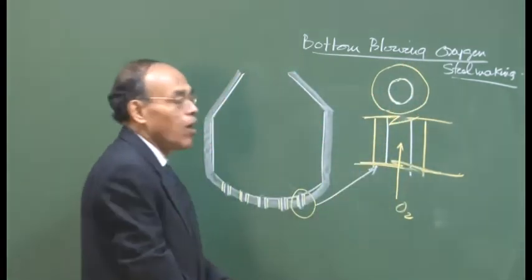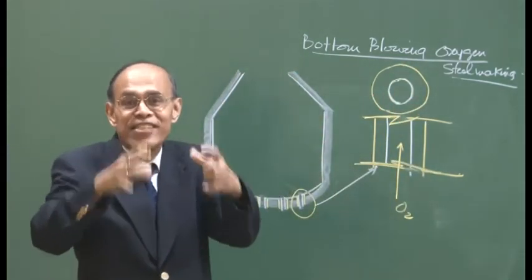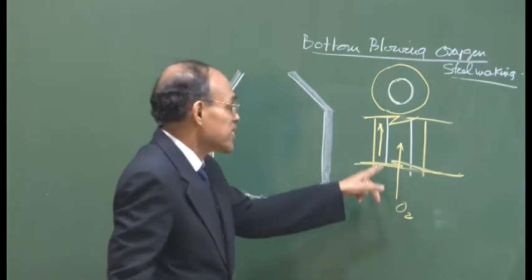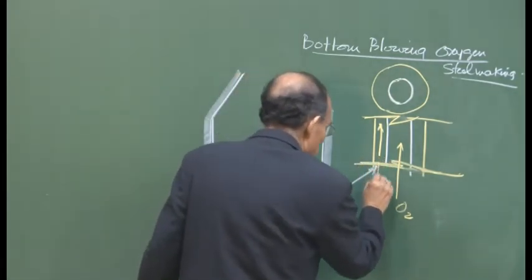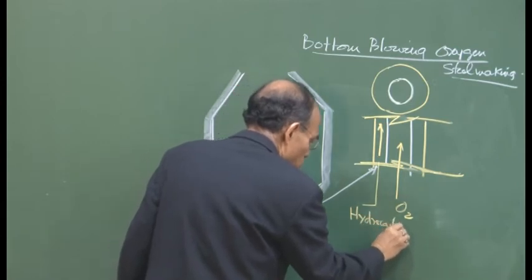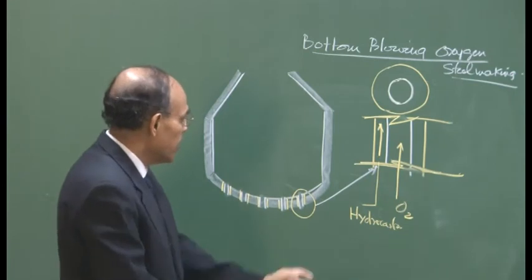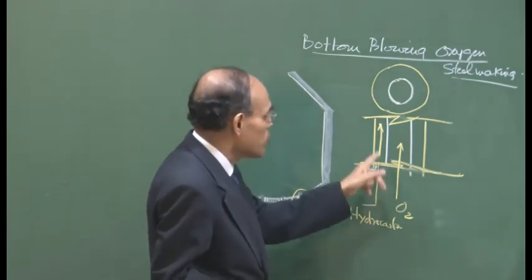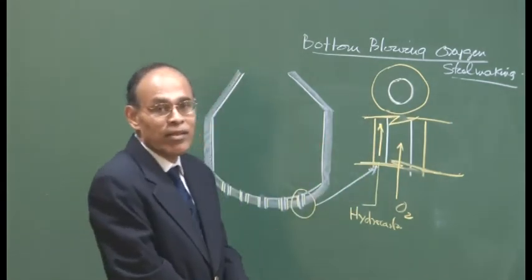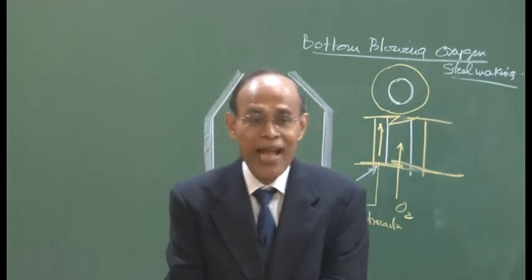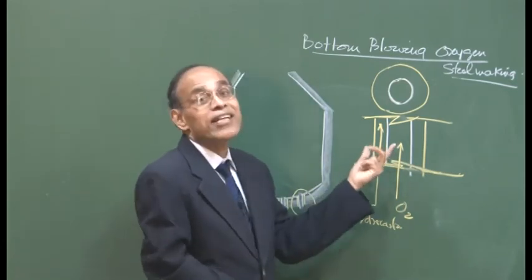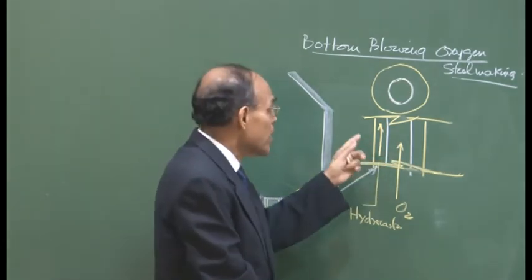This is the top view of the coaxial tuyeres. These are two concentric cylindrical pipes. So, there are two gases which are flowing here. Inside is oxygen and the outside one is a hydrocarbon gas like propane, etc. Okay. Now, when you use hydrocarbon gas and oxygen here, because there is an intense heat, the cracking reaction takes place. The hydrocarbon will dissociate, and the cracking reactions are known to be highly endothermic reactions. So, there is a local